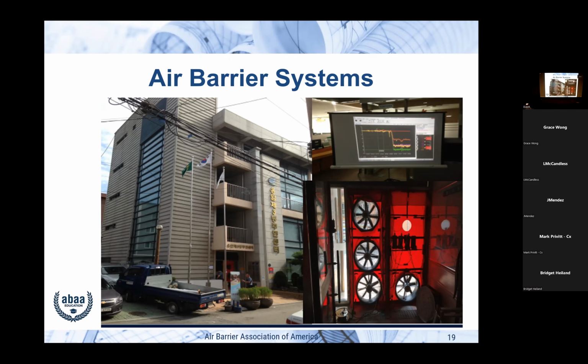And then your third test is for the fabric of the building, for the air barrier itself. And that you seal off all intentional openings so that everything is airtight, and the only way air can get through your walls or your ceiling or whatever it is is through the holes that you can't see. And you can do those 2 tests very simply, very easily. So it's always good to do those both.